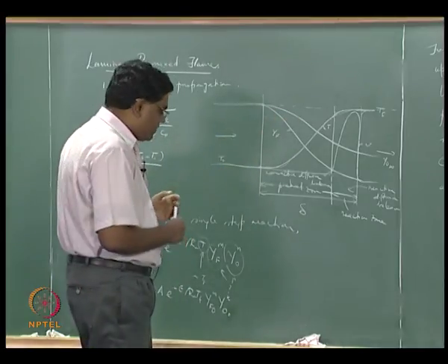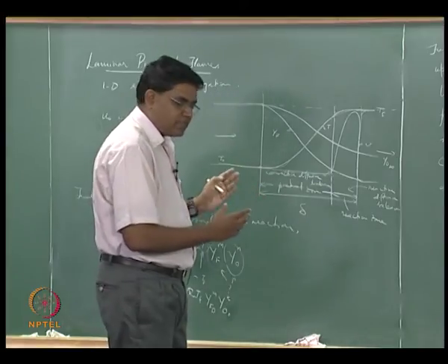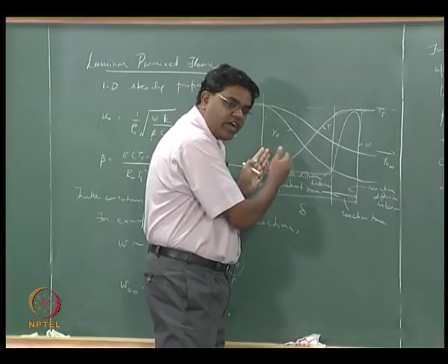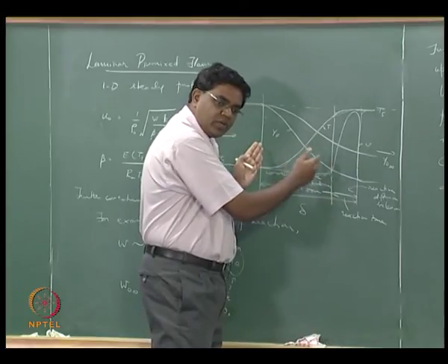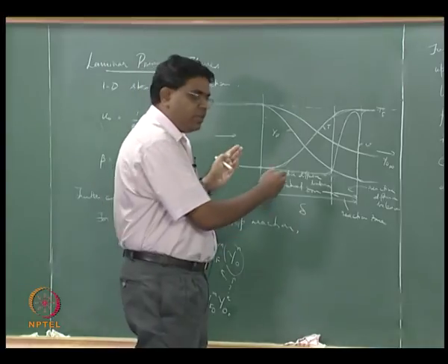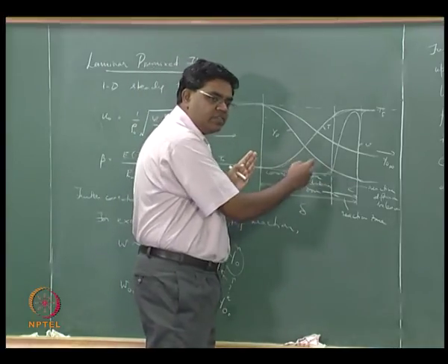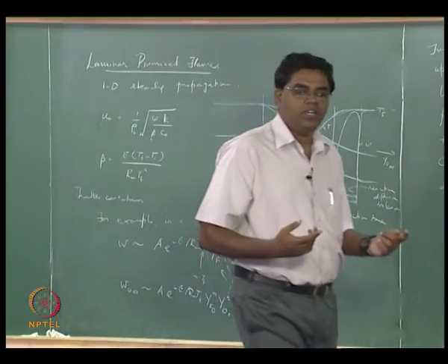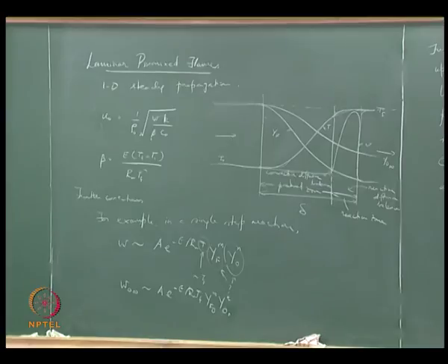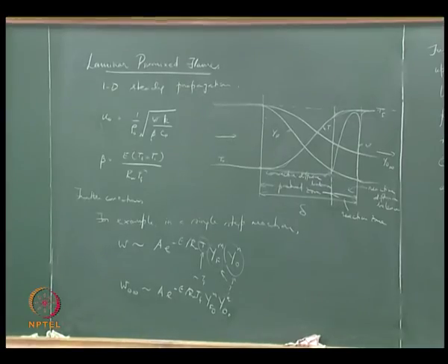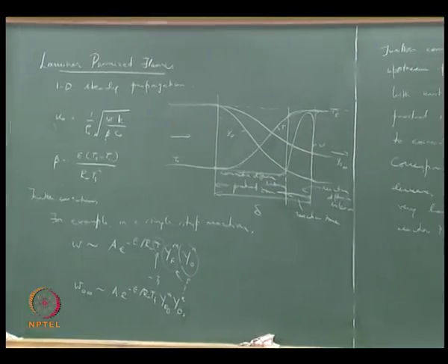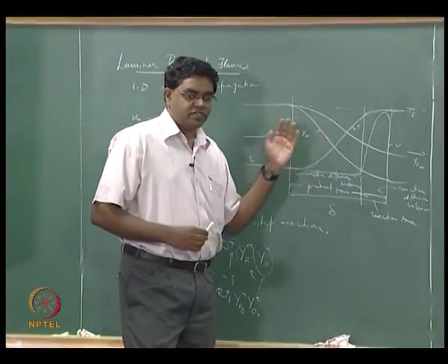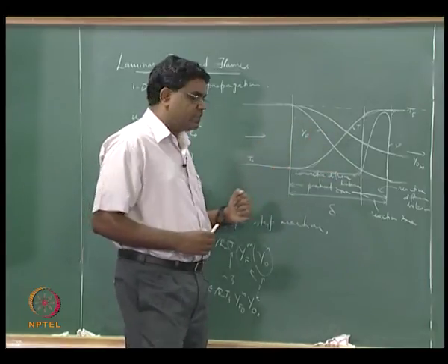That means as far as the reactant species mass is concerned, you have a convective diffusive balance in this region for the reactant species mass. If you assume that the length scale of this balance is the same as the temperature profile, then we are implicitly assuming that the Lewis number for the reactant species is also equal to 1. That means the reactant species can diffuse just as well as it can conduct heat, is what we are basically assuming.